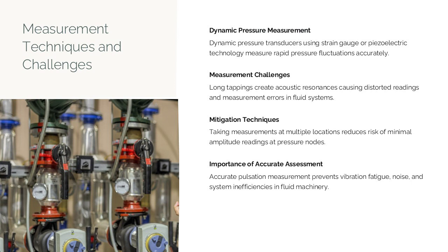A key challenge is introducing the transducer into the fluid stream without creating measurement errors. Long tappings can cause acoustic resonances in the resulting dead leg, distorting readings. To mitigate this, measurements should be taken at multiple locations along the same line, reducing the risk of capturing data at pressure nodes where amplitudes are minimal.